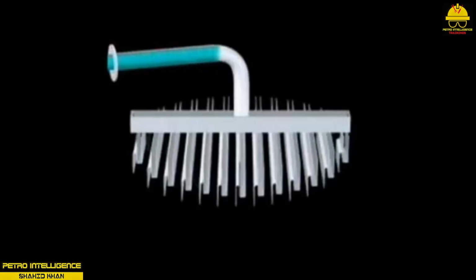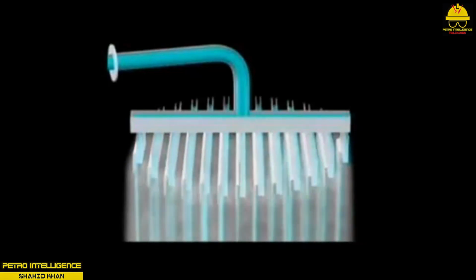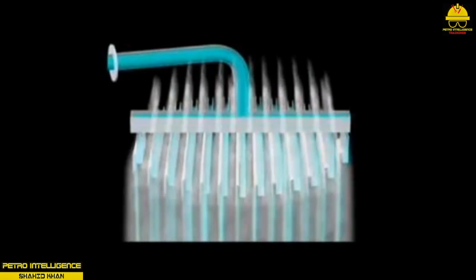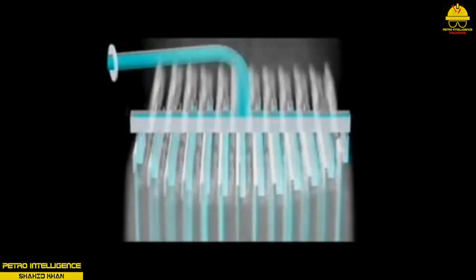Liquid distribution and redistribution. Packed distillation columns use liquid distributors to disperse fluid evenly over the top of the packing. This process plays an important role in the efficient operation of the column. Poor liquid distribution reduces vapor-liquid contact and promotes channeling.